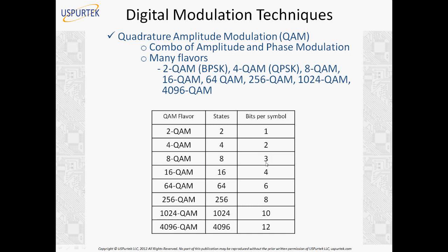Typically, as an example, LTE and wireless LAN very commonly use 64QAM. That means in just one symbol you have 6 bits, and you have 64 states. 2 exponent 6 is 64. You could go even higher, but as you go higher in the number of states, the modulation and demodulation becomes more challenging. Because you have so many states, you need more and more powerful electronics, sensitivity, DSP processors and new algorithms to differentiate the states as the number of states increases.